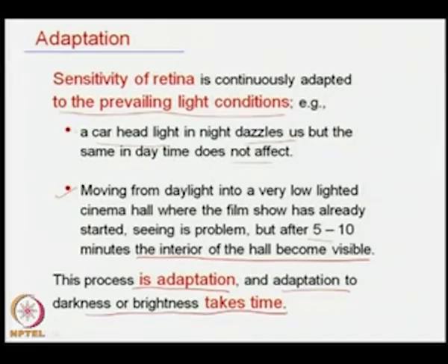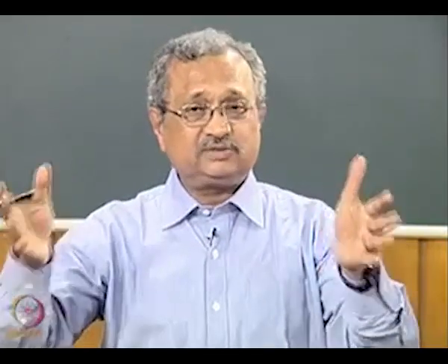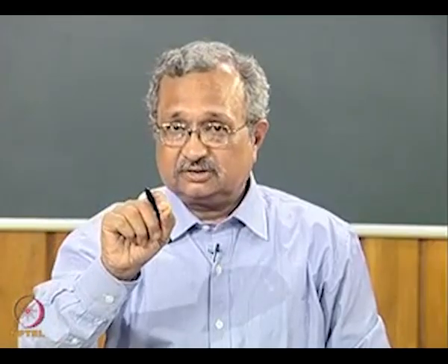In that case, if a person has to enter into a dark place, either there will be another space in between where an intermediate lighting situation exists, or some gradual decrease or increase of light condition should be maintained and some time may be given. With this we may create a special exhibition hall kind of appearance, where people need to concentrate on some specific object, whereas the total light condition may differ.